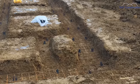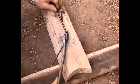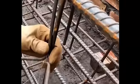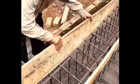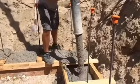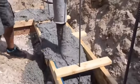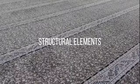The purpose of this reinforcing mesh is to increase the tensile strength of the foundation, making it capable of withstanding the heavy loads given by the steel structures of the mosque. Once reinforcement is in place, the construction process proceeds to the installation of formwork, which acts as a temporary mold to shape the concrete into the desired structure. The construction process culminates with the pouring of concrete into the formwork. This stage comprises the meticulous placing and positioning of concrete, ensuring a uniform distribution and compression around the reinforcing. The concrete mixture is designed to fulfill specific structural demands and environmental circumstances, increasing the foundation's durability and lifespan. After pouring, the strip foundation undergoes an important phase of curing, allowing the concrete to achieve its maximum strength.